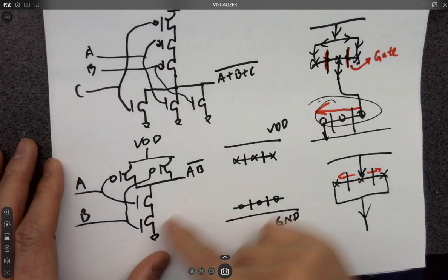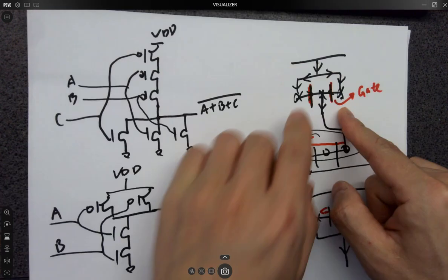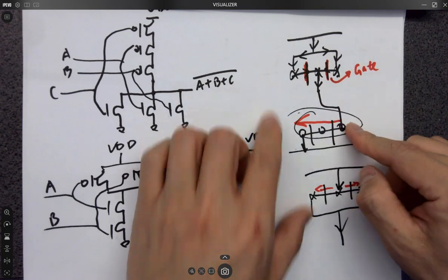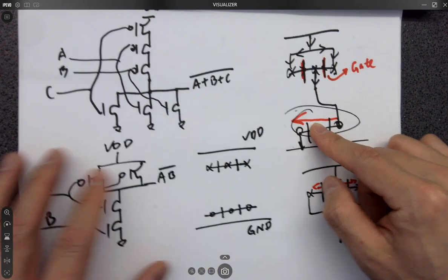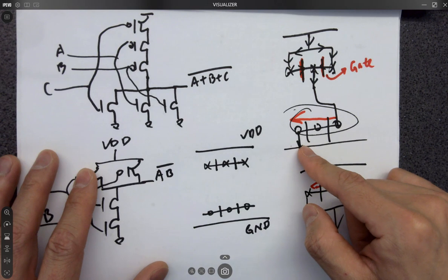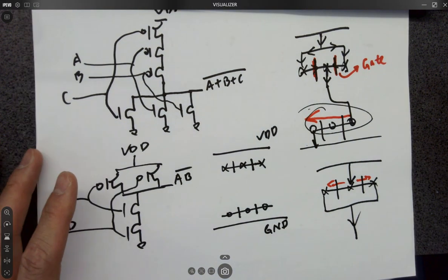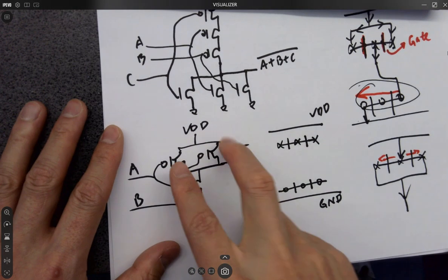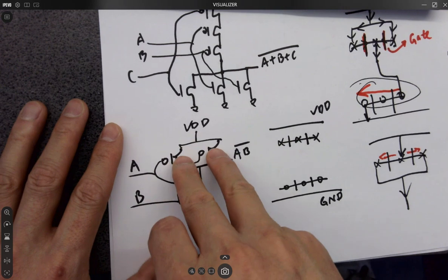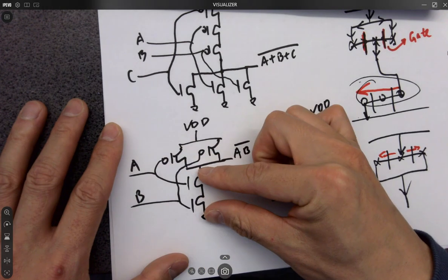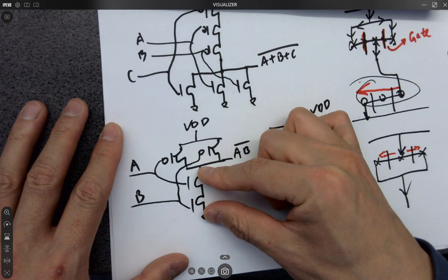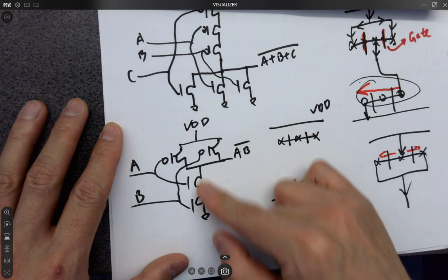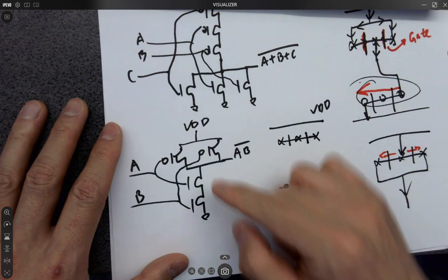Okay, so this is a NAND gate layout, a stick diagram. In the future, when you are doing the layouts, you place two transistors, you'll do a wire here, and you introduce another wire here and connect two NMOS, series NMOSes at the bottom and short it to ground. What about the gates? You have A and B, right? Even though the two parallel transistors are equivalent, and these are equivalent as well, it probably matters for the position of these two transistors because one's on the top, one's at the bottom.